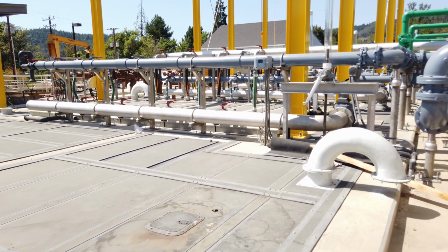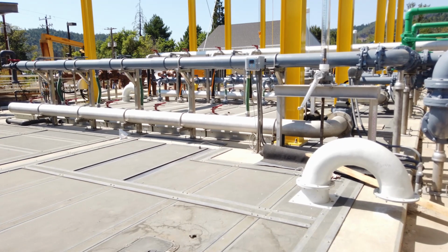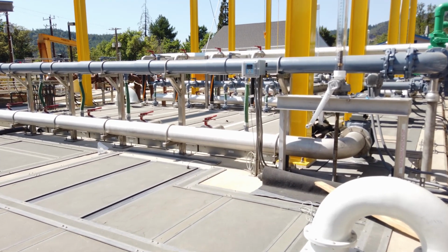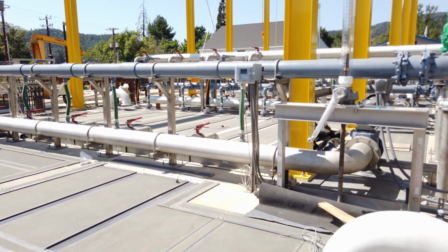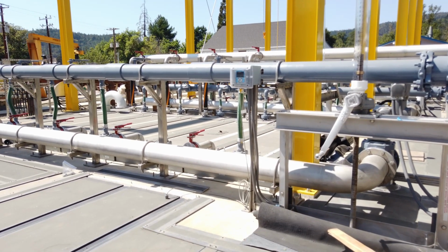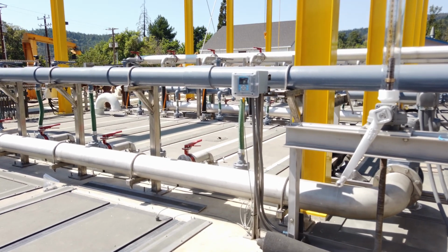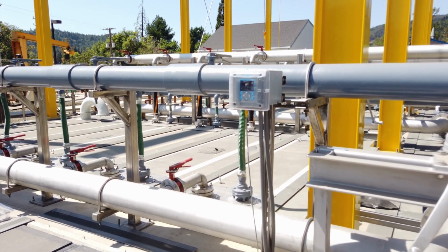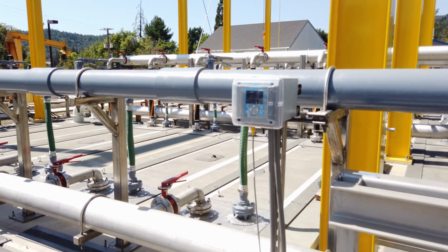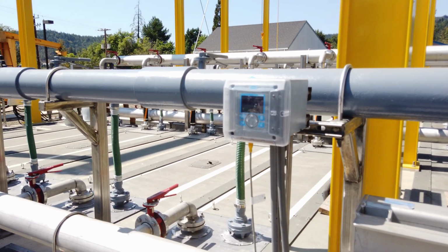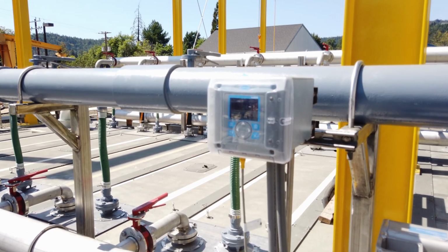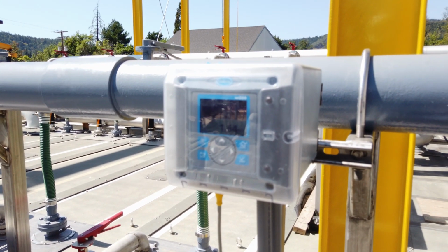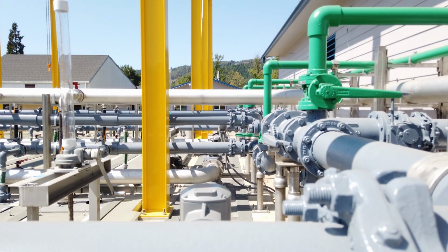Also, during the summertime, when discharging to the South Umpqua River, we have a low phosphorus limit. This time of year, the phosphorus limit is less than 1 milligram per liter. To achieve this, we are injecting liquid alum into the pre-aeration tank to chemically precipitate phosphorus and remove it through the waste stream. To accomplish this, duplex chemical feed pumps located in the chemical room convey liquid alum to the pre-aeration tank for flocculation. We're now viewing the distribution channel.